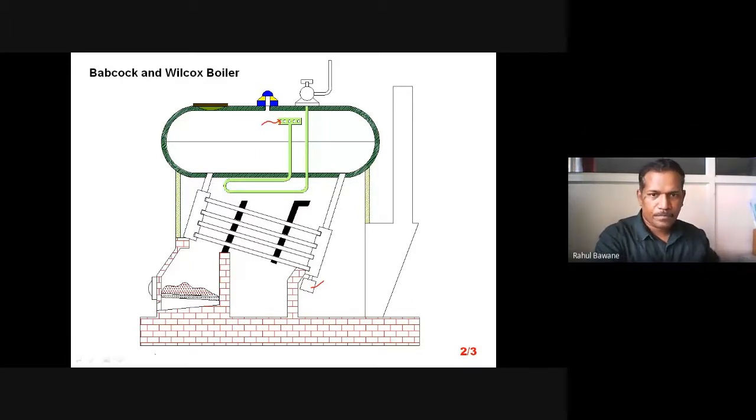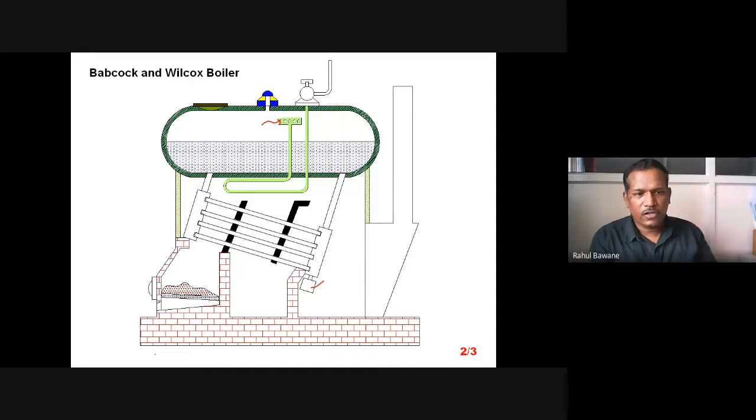So the furnace is there. Now with the help of the feed water connection, remember the boiler itself has a very high pressure. So when we supply feed water, because we are feeding that water for generating steam, it should not be like that the inner pressure will push water outside through the feed water connection. So the feed water connection always has a one-way valve, a non-return valve. That means water can enter the boiler, but it cannot be removed from the boiler, even though the boiler's inside pressure is high. So with the help of the feed water connection and non-return valve, we supply fresh water, removing all impurities before supplying it. This is the ash pit door.